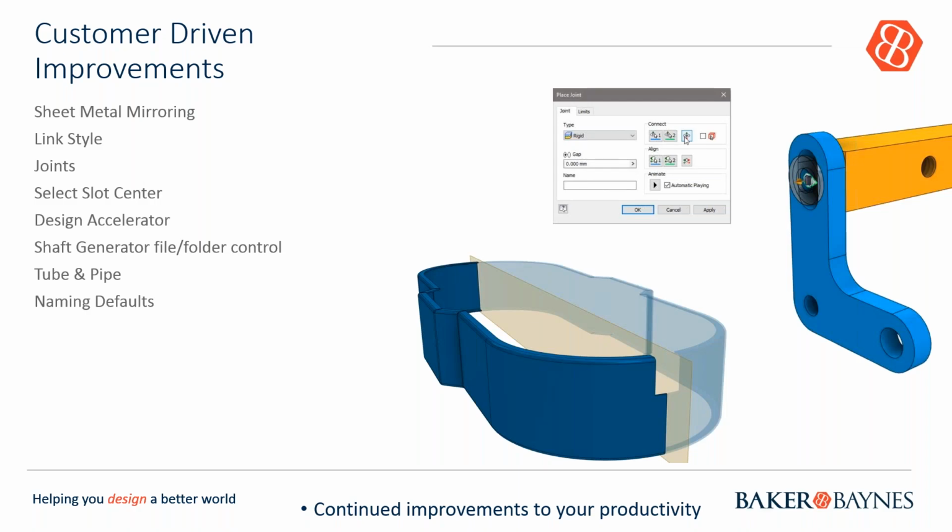So let's have a look at some of them. Okay, so we find in the customer-driven enhancements, mirror components such as sheet metal enhancements that have been added there. The mirror component command now recognizes a sheet metal part and lets you link the sheet metal style of the source component to the mirrored copy, which is really cool. The joint create enhancement: you can now select the center point of a slot to define a joint.